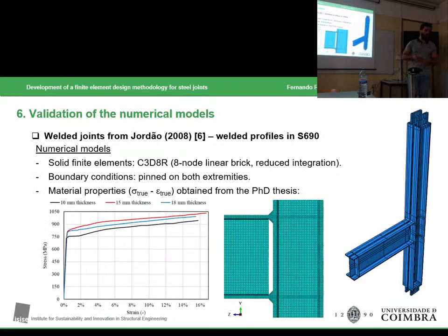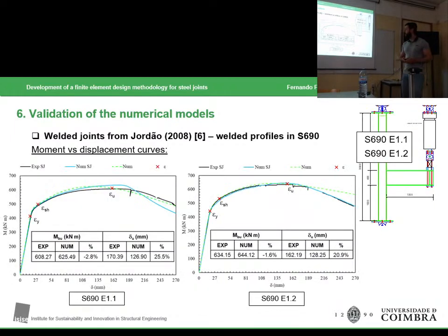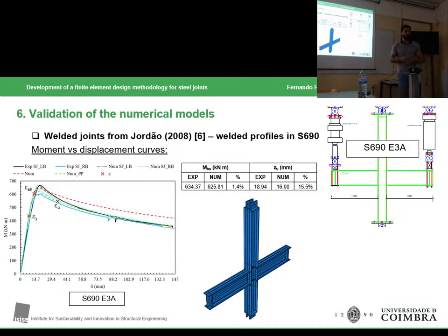Okay. So this may be attributed to some scatter in the columns, I don't know, the experiment. Okay, this was a general question. You were mentioning that you had applied some relative axial load. So what's this relative axial load in slide number 43? But you could answer it. Okay, so this is just a ratio of the column axial resistance, the values 0.3, 0.5, and 0.7. So this is just to compare to the Eurocode, since the Eurocode says there's no difference.